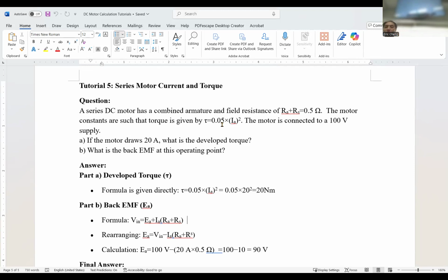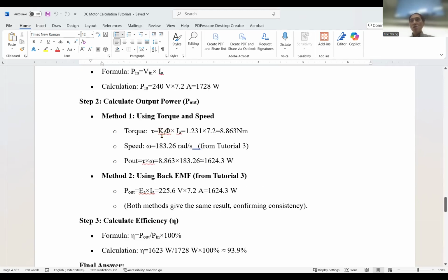Also the torque constant can be different now, because in a shunt motor we independently control the magnetic flux to the motor. So the torque constant will not just equal a constant, it may be controllable. In the previous equation, you can see the torque is proportional to the torque constant times the phi. If it is a separately excited motor using shunt, then this phi is also controlled by the shunt resistor and the input voltage.